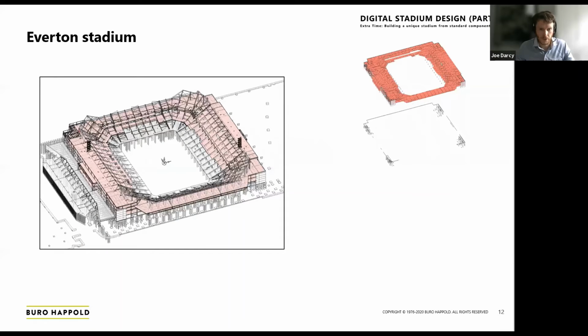There are also precast beams, some of which include notches enabling stitching into the lattice slab itself. The twin wall system, similar to the lattice planks, is precast biscuits with a girder system between them, which is then completed with in situ fill and stitching reinforcement between the different planks, and also precast columns as well.